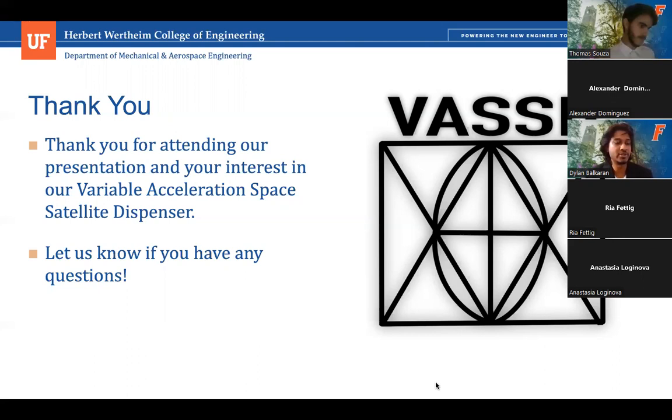Basically, in our cost analysis, we have stock that we bought, and we would take a bandsaw, cut them into separate blanks and then CNC them. And the way we determined the triangulated holes within the diagonal portion of the gusset was by doing FEM.